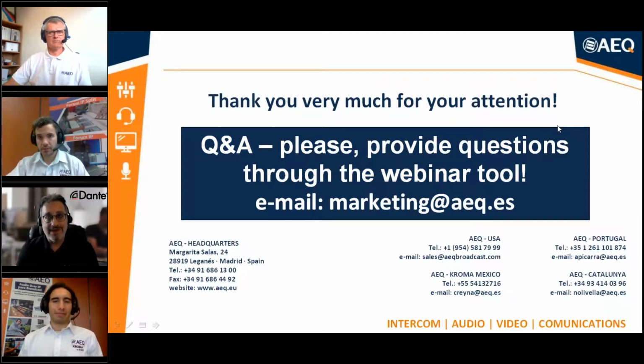Right, the way that primary and secondary work and a PC connected on primary and secondary, we'd have to look in more detail at what software they're using to do that. But normal regular Dante equipment, which have a primary and secondary, basically the secondary is an exact copy of everything that is happening on the primary. There is no difference between one and the other. So any change that you make in Dante Controller, normally you're making it on the primary, but in the case of Dante's primary and secondary implementation for redundancy, it's happening simultaneously on the secondary.